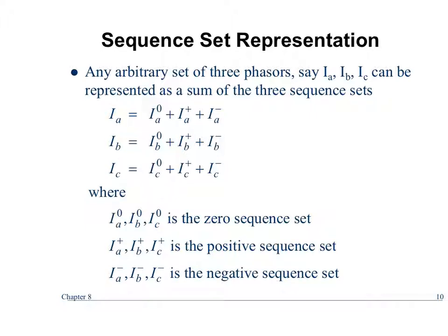If it's all molded case circuit breakers with trip units, all you're monitoring is phase currents. But if you're going to get to the next level of sophistication, you're trying to protect a 1,000 horsepower motor, maybe calculating unbalance is a very important quantity to you. Okay? So it might not be as important if you're working at a paper mill, but all the concepts apply, whether it's 480 volt distribution or 48,000 volt, 480,000 volt, it's all relevant. Okay, any questions?